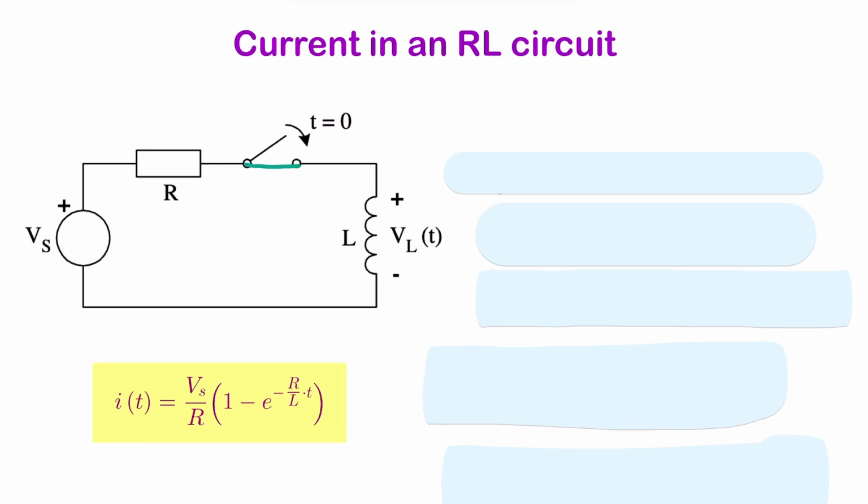so when we initially have a circuit, the inductor is not going to allow current to pass. So initially it's going to resist and it will behave as an open circuit. And then the current will then increase with time. So we have current as a function of time.